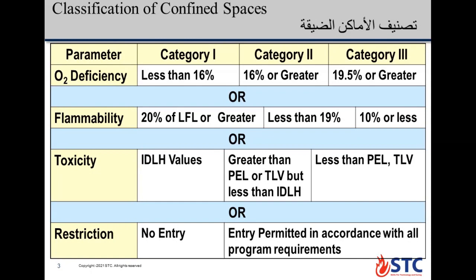And if the flammability is less than 10 percent LFL, and the toxicity is less than the BEL or TLV, the ratio of toxicity is permissible, then you may work.